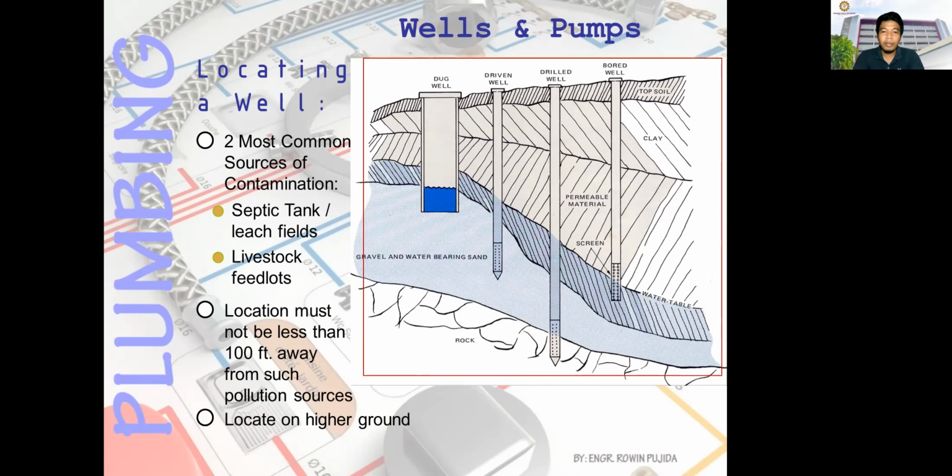And locate on higher grounds. You should locate the wells on higher grounds. The deeper the well, the better for natural filtration. Since the standard wells should be at least 15 meters in depth. Okay.